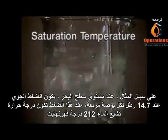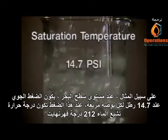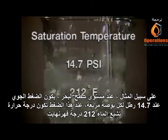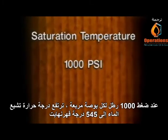For example, at sea level, atmospheric pressure is 14.7 pounds per square inch. At that pressure, the saturation temperature of water is 212 degrees Fahrenheit. At a pressure of 1,000 pounds per square inch, the saturation temperature of water rises to 545 degrees Fahrenheit.